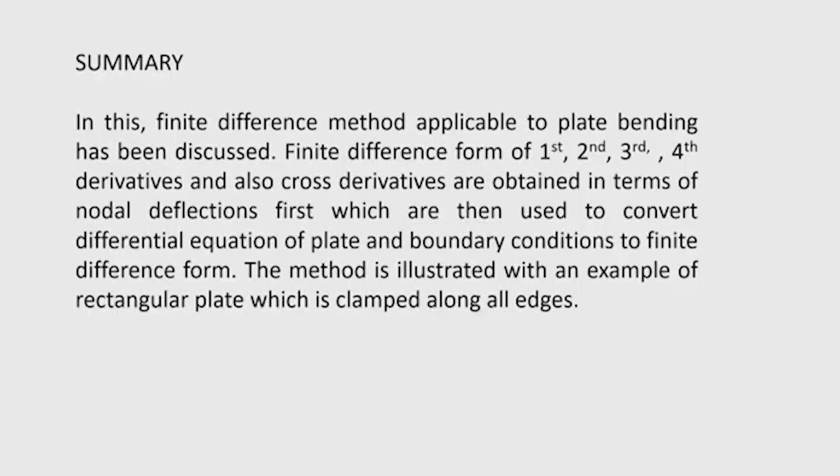The finite difference forms of first, second, third and fourth derivatives and also cross derivatives are obtained in terms of nodal deflections first, which are then used to convert the differential equation of the plate and boundary conditions to finite difference form. The method is illustrated with an example of a rectangular plate which is clamped along all edges.